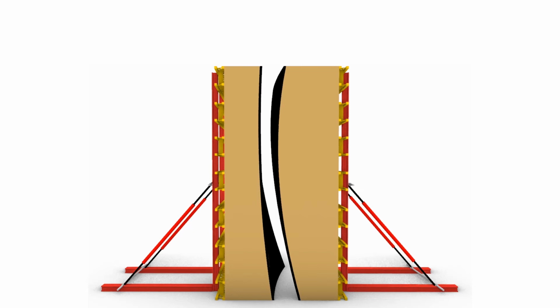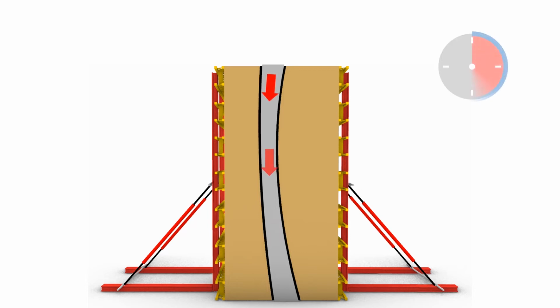If we look at the side of the curved form, brace frames are supported to transfer concrete pressure into the substructure and foundation. When concrete is cast in this formwork, the pressure at the bottom increases over time due to the fluid pressure of the concrete that is not hardened. If the formwork does not withstand increased pressure, it will cause failure.